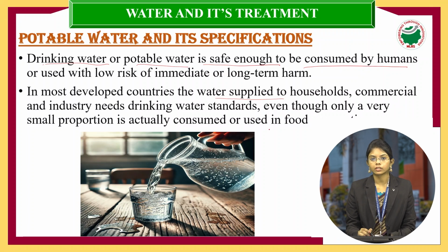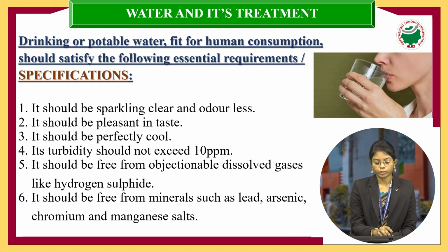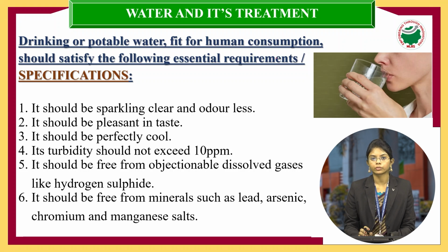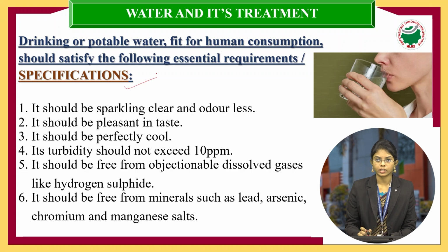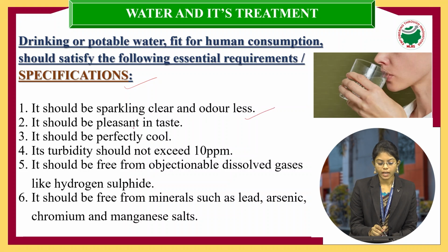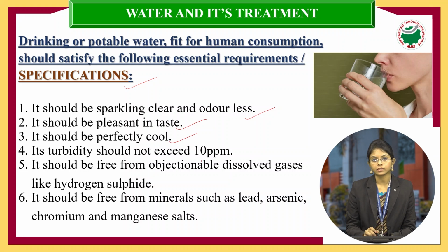To improve the drinking water standards, we purify or treat the water. Drinking water or potable water is fit for human consumption, so whatever water we are going to consume should meet some specifications. Coming to the potable water specifications, first it should be sparkling clear and odorless, the taste should be pleasant and perfectly cool, and its turbidity should not exceed 10 ppm.